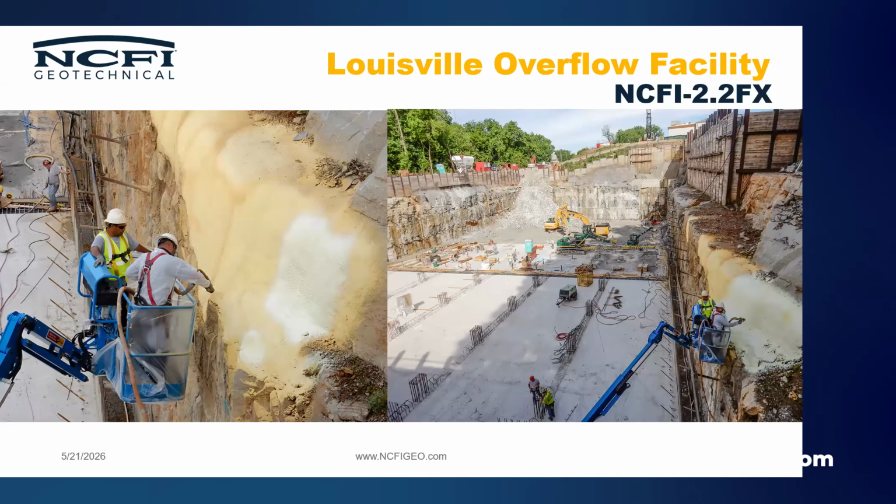As you can see, anywhere they had fallouts from the rock there, they just built it up, and you can see how the UV had an effect. This was probably day 2, and the stuff that was in there the previous day is starting to yellow a little bit. So polyurethane is not intended to be left exposed for long periods of time, but it will start to yellow a little bit, but the degradation is minimal at that point. It's basically just going to start to get a little flaky on the outside, but less than probably 1,000th of a millimeter of material loss over, say, a week period of time left being exposed. It's not going to go away that quickly.